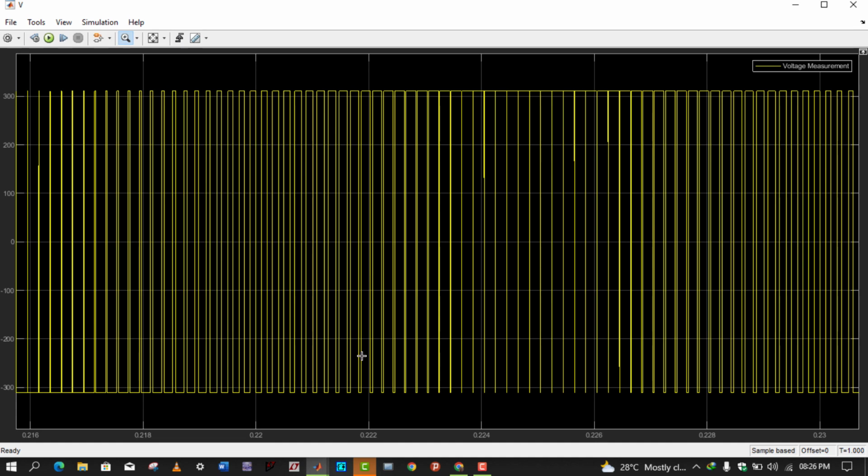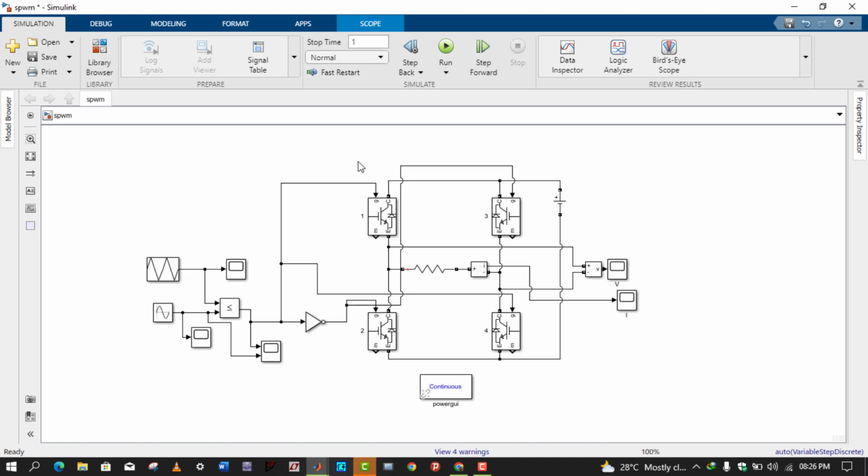So using this technique, we can decrease the THD of the inverter, which is a good thing for us. As we know, if we design a simple square wave inverter, it will have a THD of about 50%. So it will generate more heat, the efficiency of the inverter will be very small, and it will generate heat in the inverter and in the load. And if we use this topology, like SPWM based inverters, we put a 50 hertz or 60 hertz signal in the pulses, and these pulses then appear in the output waveform, and we get the THD very low.